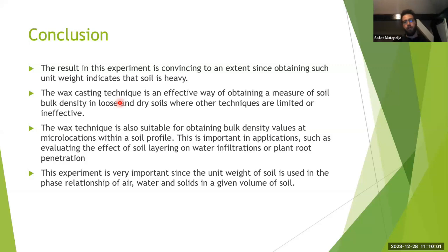Based on that parameter, you design foundations. It depends on the country. Every country in Europe already has maps with predefined accelerations, so you just get the data from the map. It is based on geophysical investigation, and in Europe you have that data prepared.